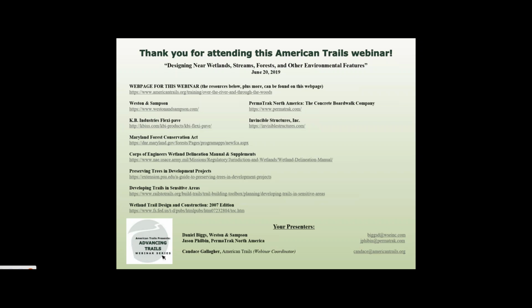All right, Charlie asks, please address the pros and cons of composite timber. Oh, wow. I'd love to take a stab at that. So pros and cons of a composite and timber. We'll start with timber because that's the most common material of choice. The pros for timber certainly are that they're readily available. The material itself, just the material, is generally going to be the cheapest one on the market. Most commonly, you would see a southern yellow pine. Some of the timber material, maybe like the ipe or the dense hardwood, is a more durable type of wooden product.